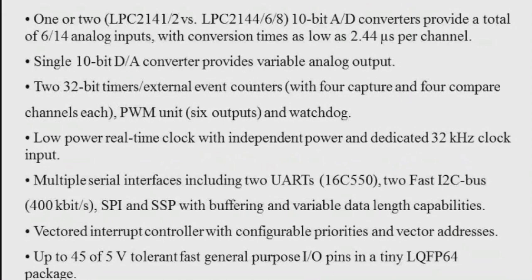Finally, multiple serial interfaces that include two UARTs, that is universal asynchronous receivers or transmitters, and I2C, inter-integrated circuit, where multiple chips are connected to the same bus and each one of them can act as a master by initiating data transfers.